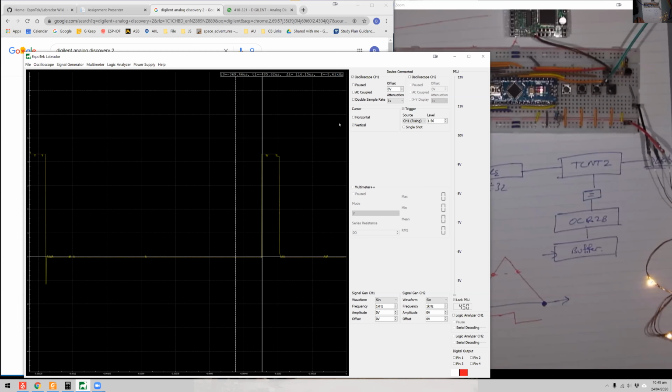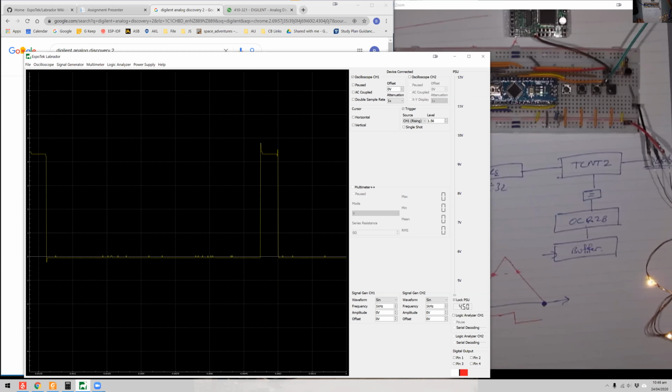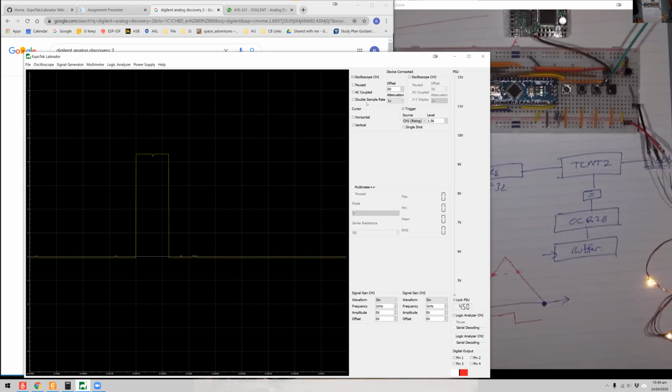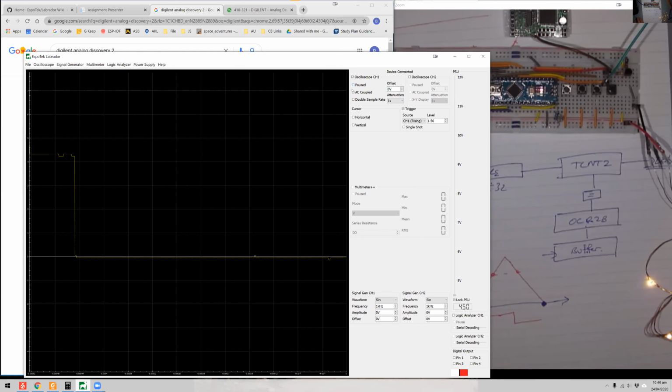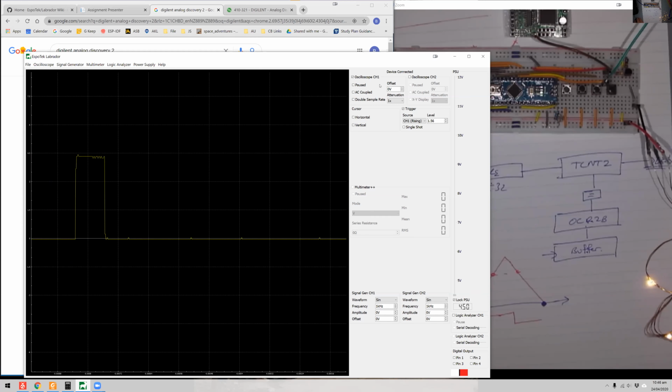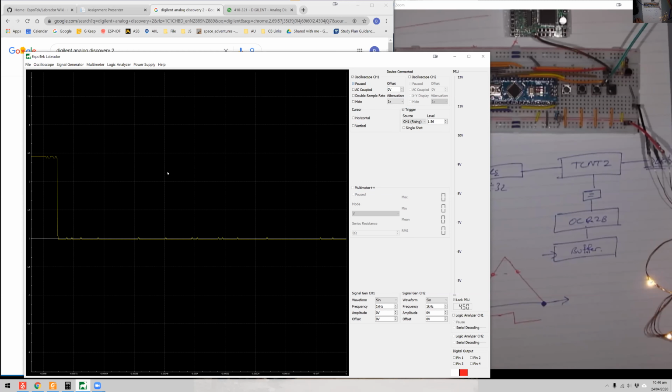So there, this is what's happening, is that you can see that these spikes are occurring, and there is something there. We're not sure exactly what it is. We can't measure it, and the reason we can't really measure it is because of the sampling rate of this device. So if I freeze this, and let's pause that, now you can see sometimes it's sampling it and sometimes it isn't. And it just depends on where it is in its sample cycle.